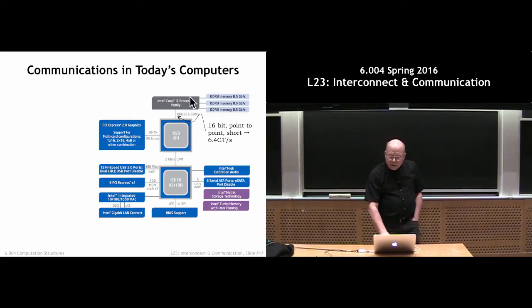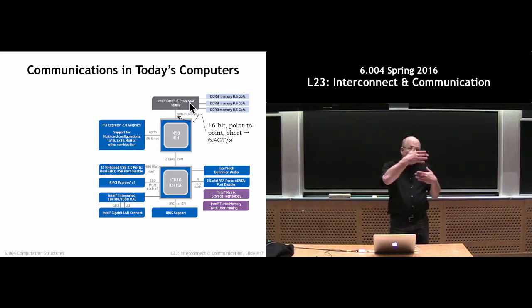So a modern computer actually has these very high performance things. There's a special communication bus, the DDR communication buses, that we talk direct. The high-end processors have three memory channels. The low-end processors have 2, so you have to either plug in 2 sticks or 3 sticks. There's basically point-to-point communication between the processor and the memory.